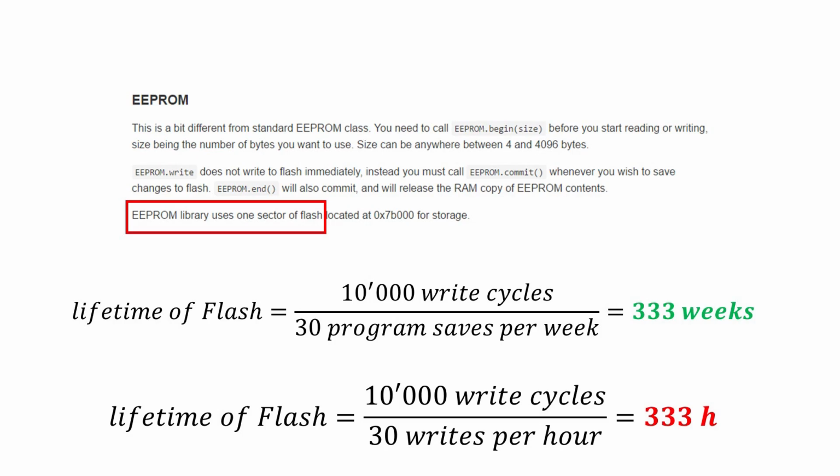We could try to store data which has to survive the deep sleep mode in the EEPROM. Unfortunately, the ESP stores the EEPROM data in flash memory, and this memory technology wears out after a few thousand write cycles. While this is no problem for storage of programs, it can quickly become a problem for counters which have to be written every hour or even every minute. But fortunately, another possibility exists.